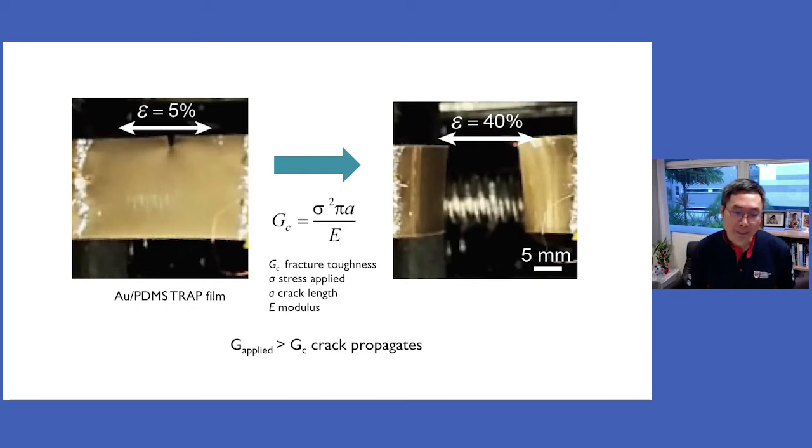So what's the reason here? In material science, you will know this is because of fracture toughness. Fracture toughness is too small. So in this case, we have a crack here, and the crack will easily migrate with additional stress applied. Now, you want to ensure this crack will not migrate. One possibility is to have a larger fracture toughness. Then, how do we do it?